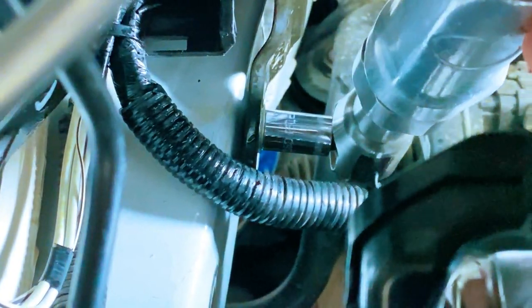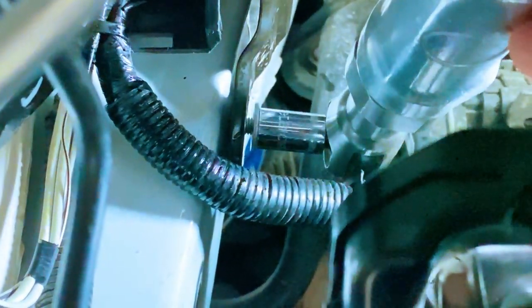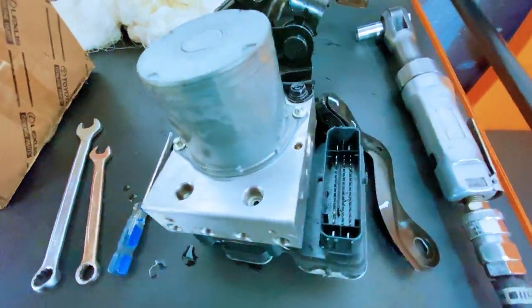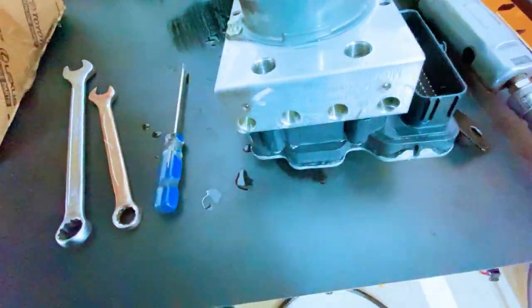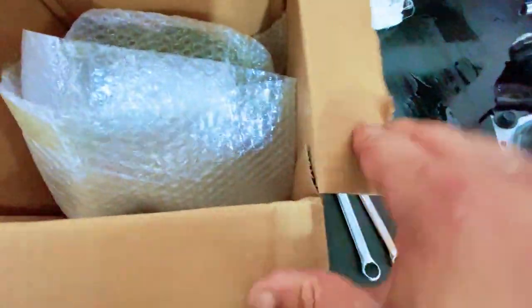but it is extremely important. A weak battery or low system voltage can create abnormal electronic brake system DTCs. So don't replace an expensive brake actuator before confirming that the vehicle has a stable power supply. After checking the battery, we move on to the DTC and freeze frame data.